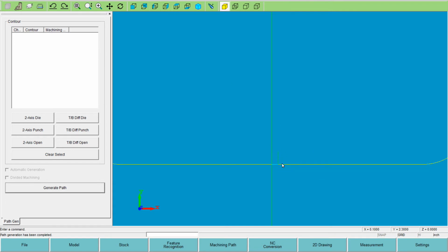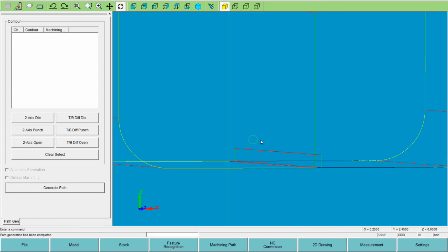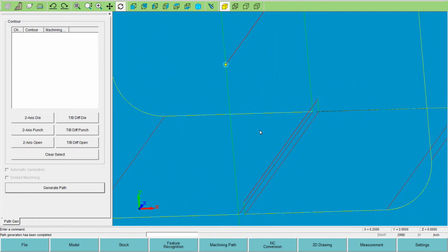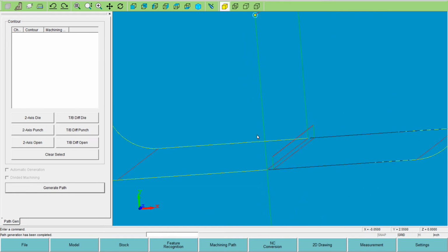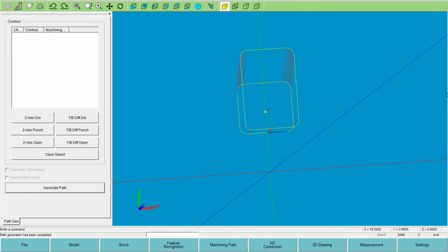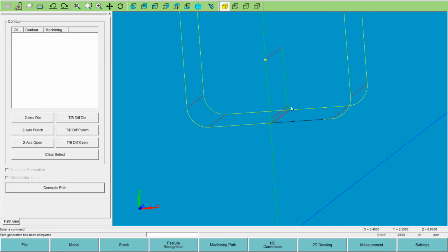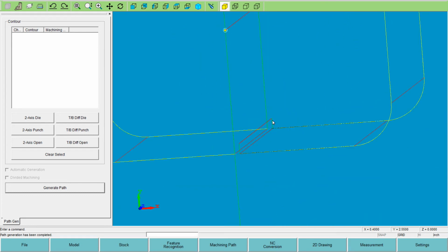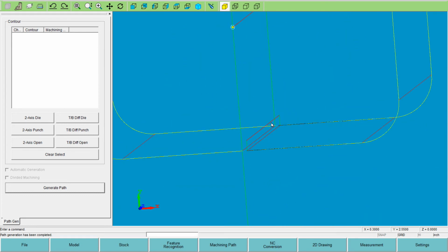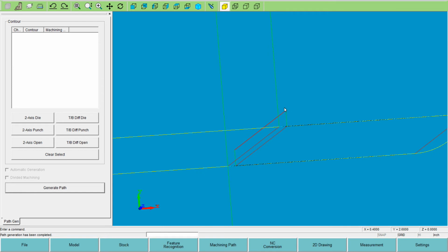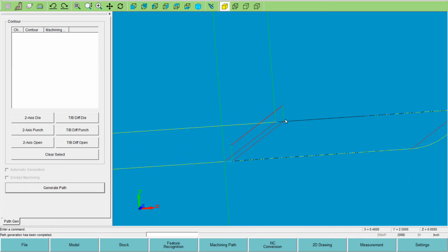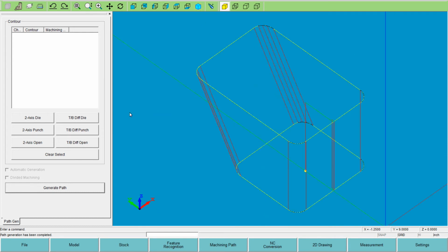So what actually happens, if you're only cutting one shape, the machine doesn't really do this little release move. You may have recognized that fact by now or not, I'm not sure. When you do multi, if I was going to cut 3 of these or 2 of these or more, that's going to be the hold on tab after the roughing, and it cuts the wire and moves to the next one. And this release move is what we're concerned about, that it releases far enough into the slug, tilting the wire back vertical, that it doesn't cut into the shape. So let me explain what I'm talking about for that. Let me get rid of this.